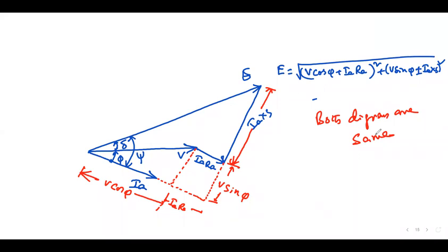And the XA value exists, right sir? XA value may exist, sir. It may or may not exist. That is fictitious, no? Imaginary. We are modeling. It causes a drop. How can you explain the drop? How can you model it? Drop in a resistance or drop in a reactance. That's all. Yes, sir. That's the reason we are representing it as a reactance. Even at unity power factor IA will exist, sir. XA value exists. Yes, yes. It is cross magnetizing. Resultant will exist.